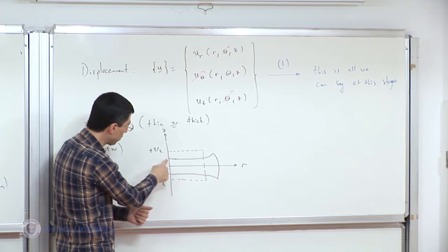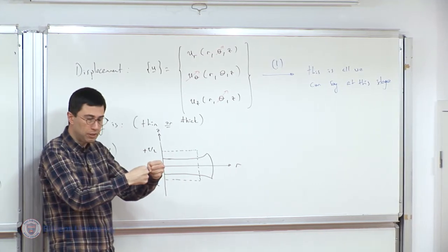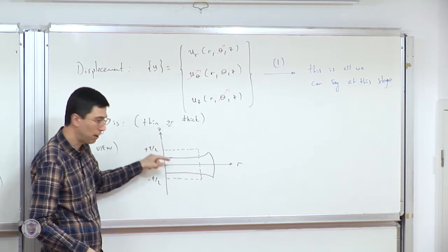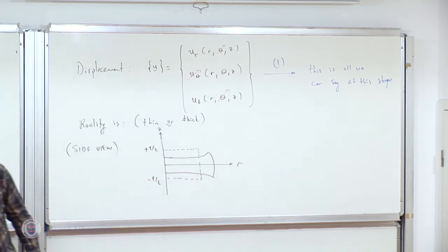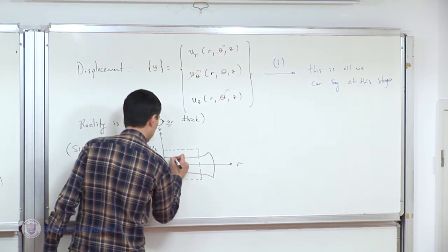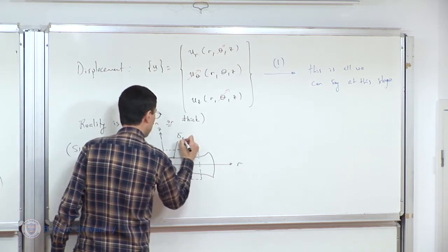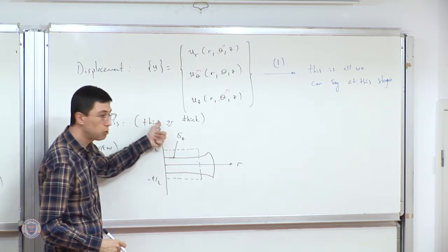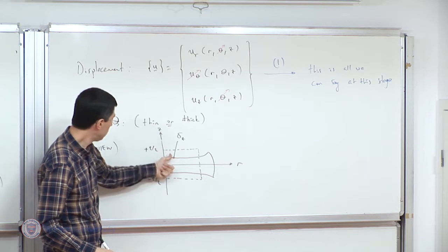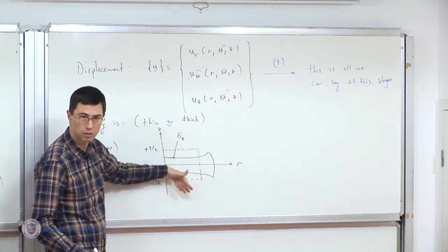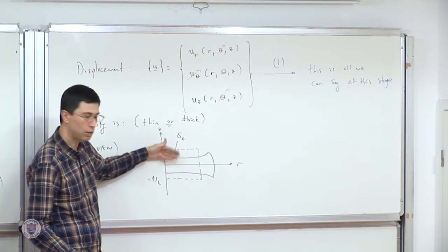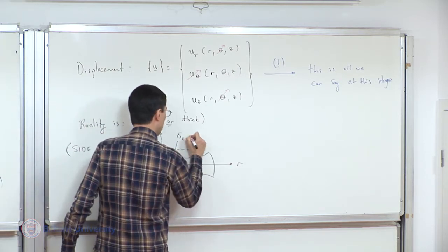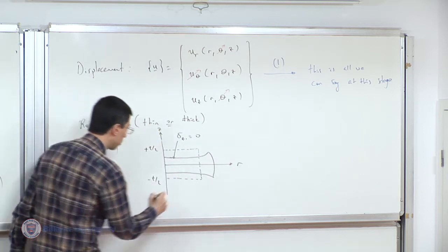Okay? And because they are so high, they are trying to pull the material in the radial and the tangential direction. In the z direction, we'll talk about the stresses, but let us first agree that at the top, at this point, sigma zz, on the plane with normal z in the direction z, it's 0. z r is also 0 because there are no tractions, right? It's traction free. And z theta is also 0. So z anything is equal to 0 on the top surface.